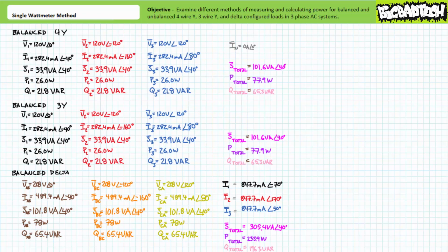Given power is a product of voltage and current, the loads in the delta configuration experience square root 3 times square root 3, or roughly 3 times the power. The larger point for this particular lecture, focusing on three-phase AC power measurement, being this. You already know how to calculate and measure power in three-phase AC systems.